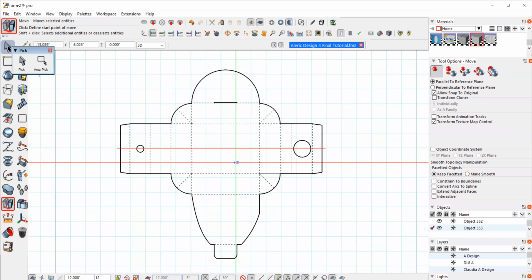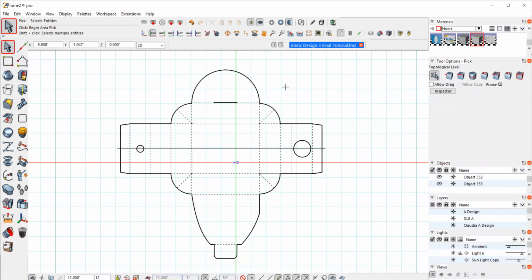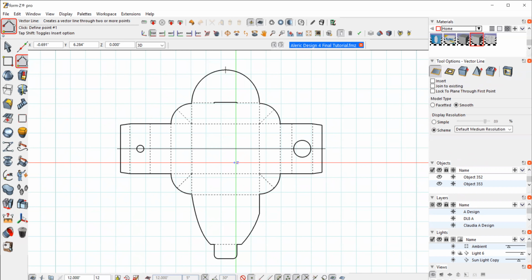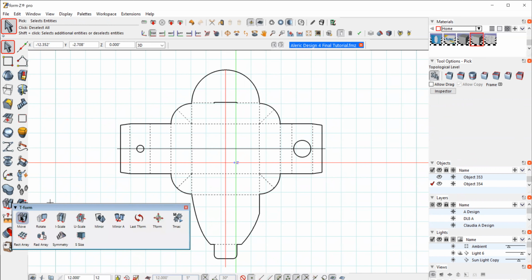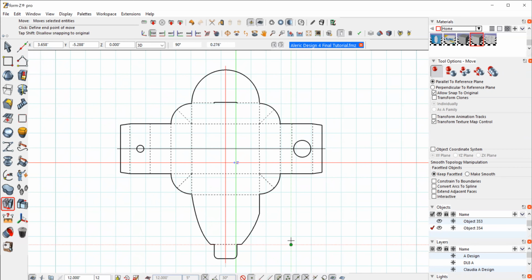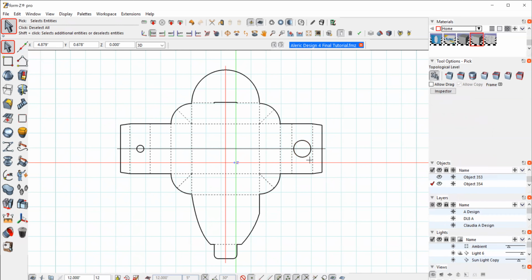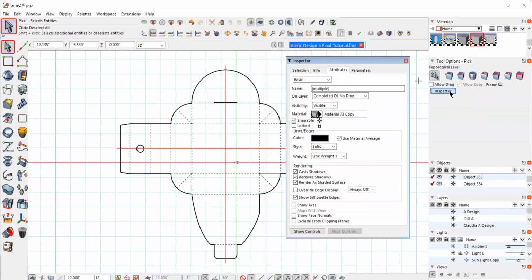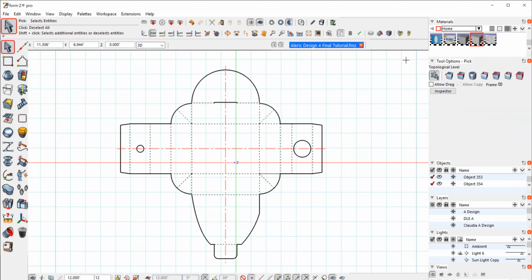So we don't want it to look like it's part of the object, so we extend it a little. I'm only doing a little bit because I got a whole series of dimensions and other things going on, but just enough to say that it's not part of the object. So I'm snapping to the middle of this arc up here, and I'm going to extend a little bit beyond the object. Select that, move that about like this. Now these two lines are center lines. So I want to give it a center line. Under Style, we have center lines. I'm going to pick the second one. It's a dash dot, long dash, short dash. That communicates center line, kind of a line language that engineers use.